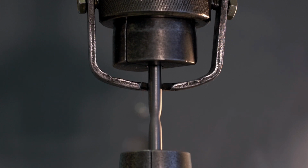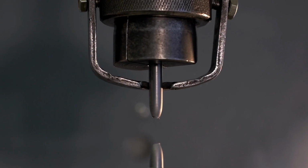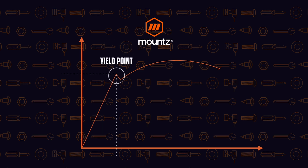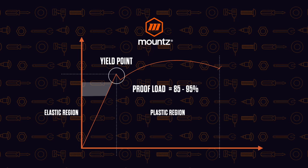And if we continue to pull, you can see it'll continue to deform, and then finally it will break. Graphically, what this looks like is we have our proof load that comes up to our yield point, and then we have our failure. Everything from the yield point to our failure point is the plastic region of that fastener, and everything underneath the yield point is the elastic region, meaning the fastener will return to its original shape if we remove the load.